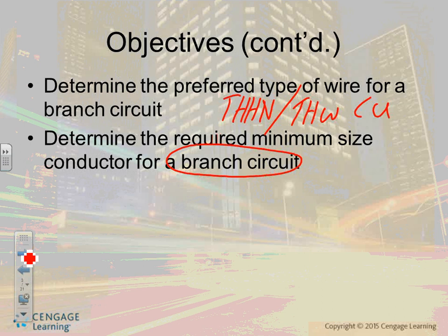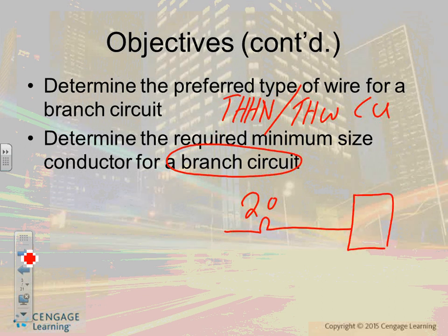Okay, when you have a 20 amp circuit, so here's my circuit. What type of load do you put here? The most notorious and famous is lighting. So you put your lighting load. We always separate light and receptacle in commercial, always. Unlike in residential, where we can mix them. And by the way, in our residential project, I'm telling you to split them too. So the rule is to split light and receptacle. You don't put them on the same circuit. Anybody wonder why?